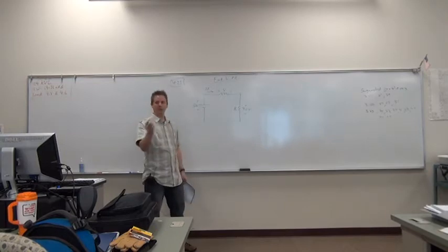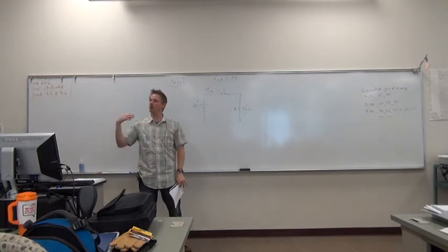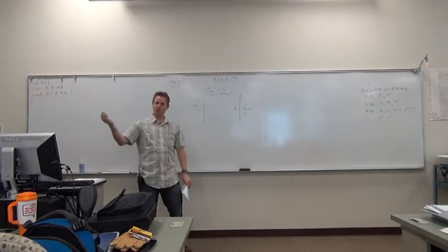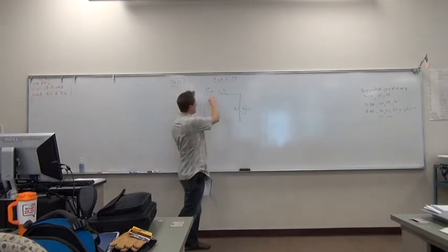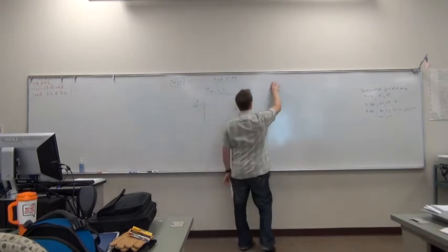If it isn't, you can go ahead and write the equation. Then you may be able to use Ohm's law, or you may be able to use another equation to solve for it, but in this case, it's going to be simple. Just go ahead and write KVL, and then you can evaluate the problem.